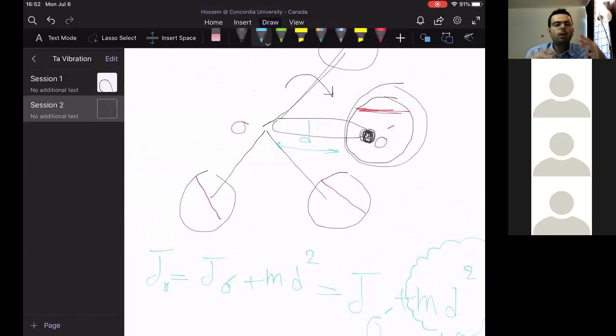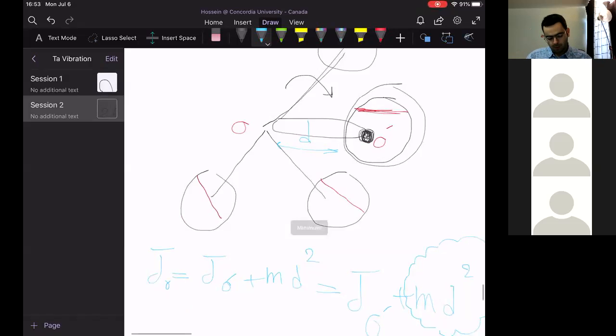So we have to use some energy to rotate the wheel also, right? Apart from the arm. So since the red line is rotating, you have to consider the mass moment of inertia of the wheel around point O prime, and in total around point O.